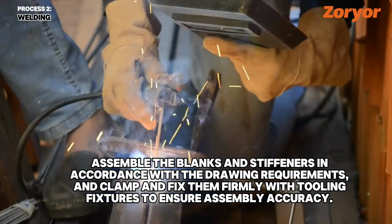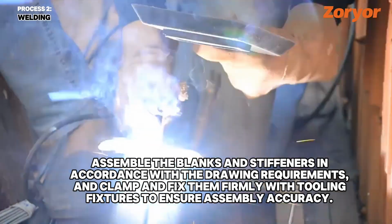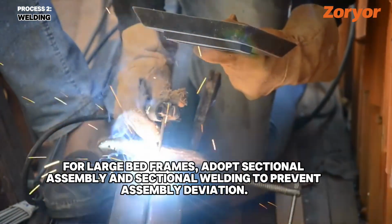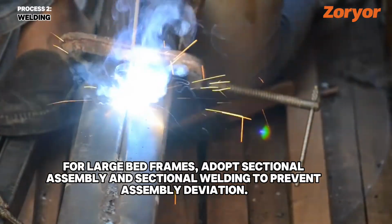Assemble the blanks and stiffeners in accordance with the drawing requirements, and clamp and fix them firmly with tooling fixtures to ensure assembly accuracy. For large bed frames, adopt sectional assembly and sectional welding to prevent assembly deviation.